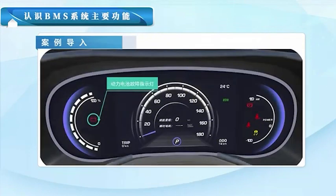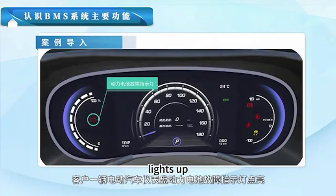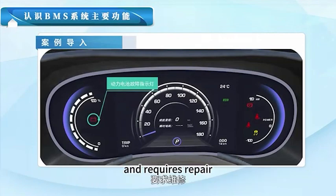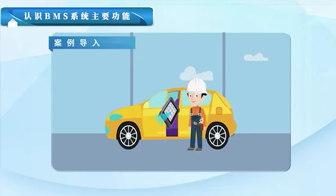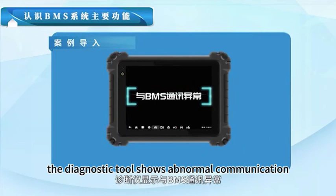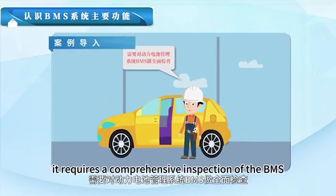Let's take an example. On a customer's electric vehicle, the power battery fault indicator on the dashboard lights up and requires repair. The technician connects the car to a fault diagnostic instrument. The diagnostic tool shows abnormal communication with BMS, which requires a comprehensive inspection of the BMS.